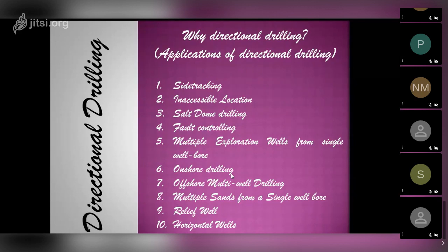And that way we drill 1,000, 2,000 meters horizontally. So if I drill 1,000 meters horizontally in a 1 meter thick reservoir, and earlier the well was vertical and we were getting oil only from 1 meter of open space, now we have 1,000 meters. So that means, not an exact calculation technically, but we can say I increase the productivity of the well 1,000 times. So that's the beauty of the horizontal well.